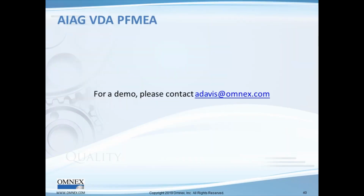Thank you, Mike. So, just as Mike mentioned, there is a 7-step process for PFMEA as well. So pretty much the same. Step 1 is still planning. There's a structure, so you can see you document the PFMEA team. Then you would also have step 2, which is the structure analysis of defining the process and the actual operations associated with each of them. So you could create your operations here, and then you could move on to the 4M.